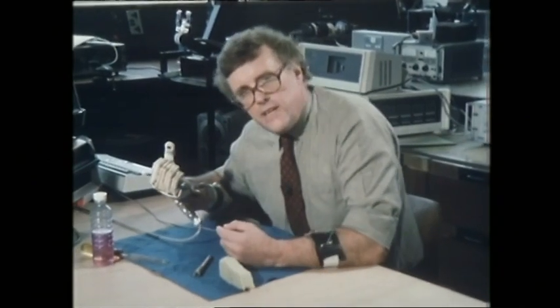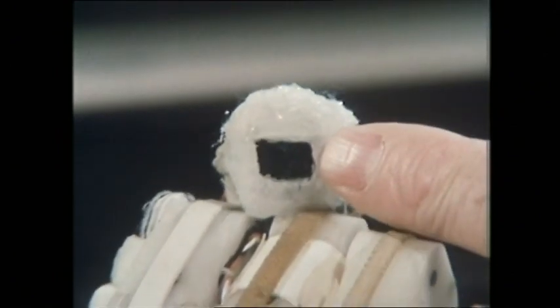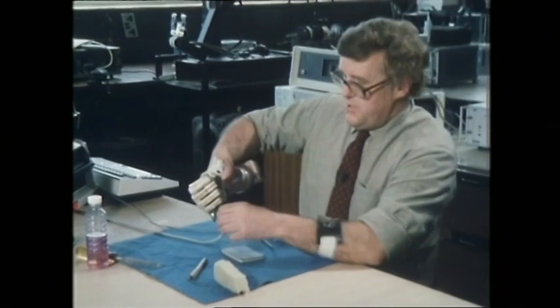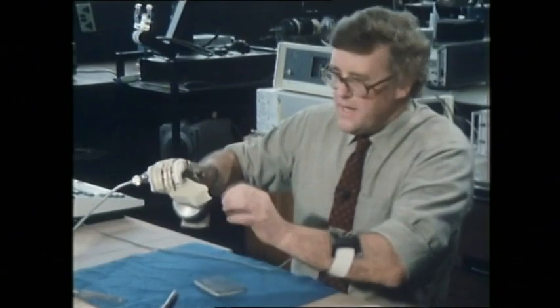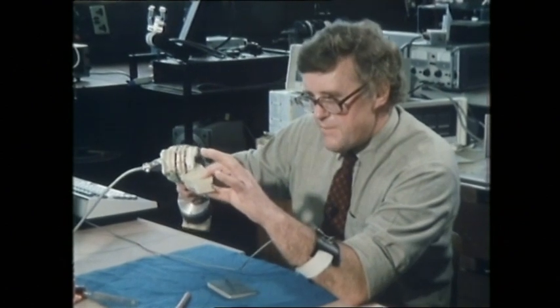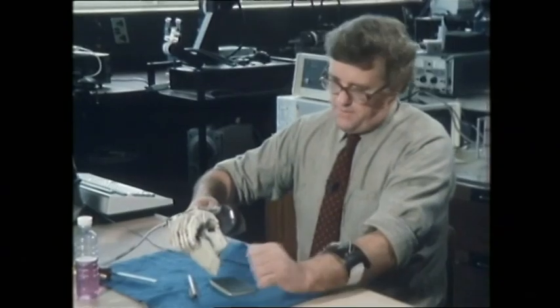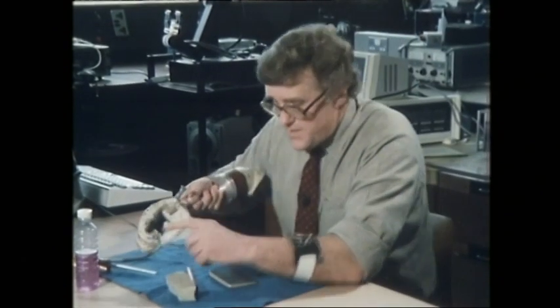There's an even more interesting sensor on this, and that's here in the thumb. And all it is is a microphone underneath this piece of Velcro. And when I want to pinch something in between the fingers, I can pick up this piece of sponge like that, and as I pull this piece of sponge out, or attempt to, the sound is transmitted from this sensor here into the computer. When it hears the sound, it automatically tenses up the hand to stop me from withdrawing this piece of sponge. In other words, it's a complete feedback mechanism. No signal from my hand is affecting it. And I can simply open the fingers and let it drop. There's another sensor here on top.